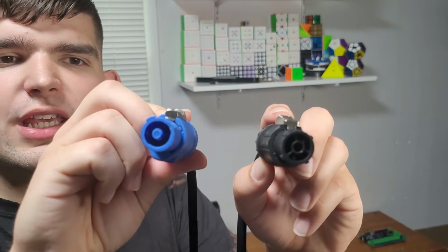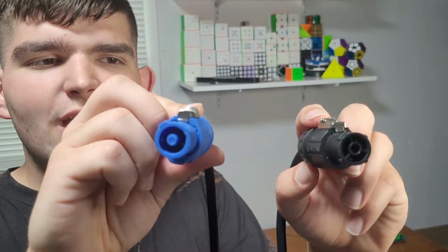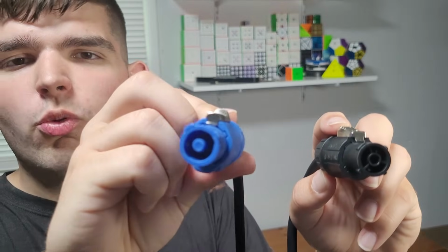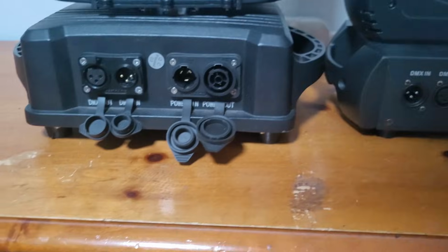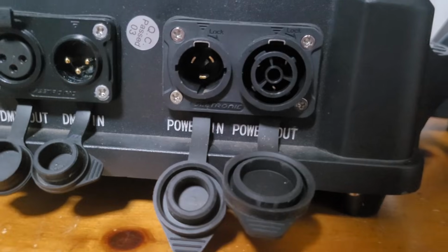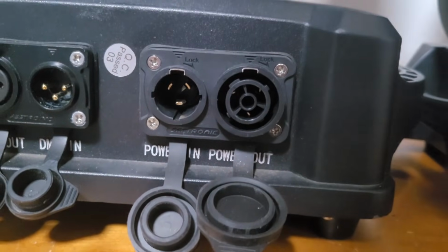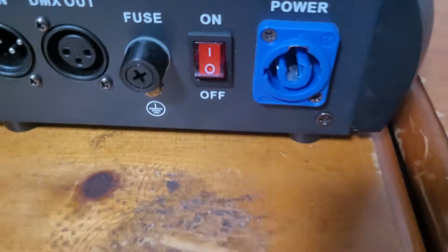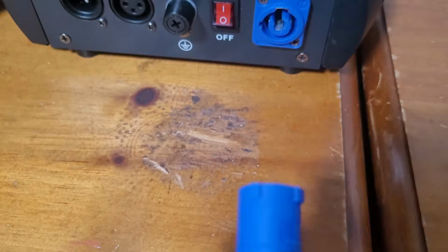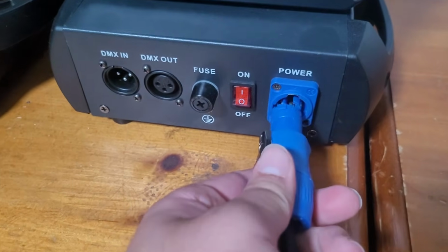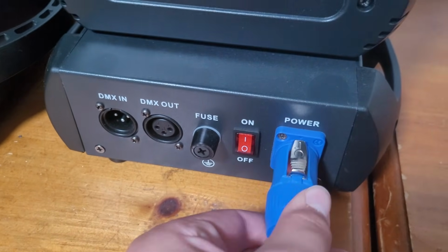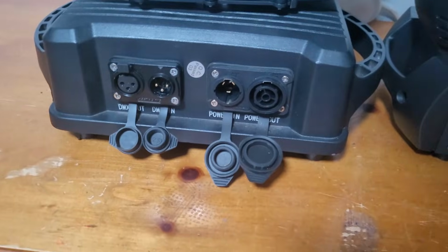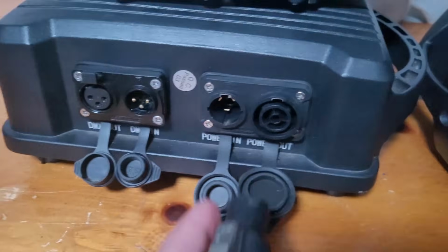Just so you can see the difference, this is what the two connectors look like. You can tell the newer one apart from the older one because of the little lines that it has connecting to the center, whereas the blue one, the older one, doesn't have that. You can also tell a little bit of a difference on the moving heads themselves. Here is the newer connector on the bigger moving head, and here is the older connector on the smaller moving head. To plug it in, you can see the little notches in the circle there, and the little bumps that stick up on the connector. You put those in slightly rotated, and then twist it, and it locks in. To unlock it, pull this back, twist it, and remove it. It's the same on here. We've got to find the power in connector, which is this one.